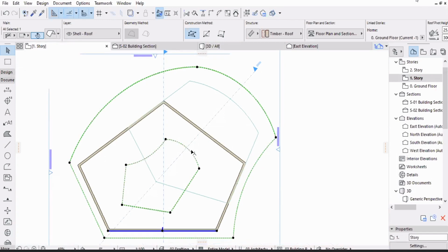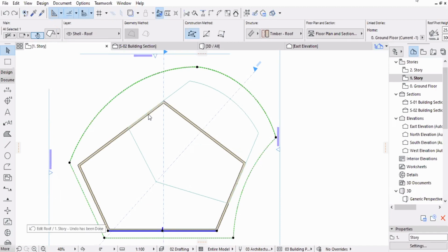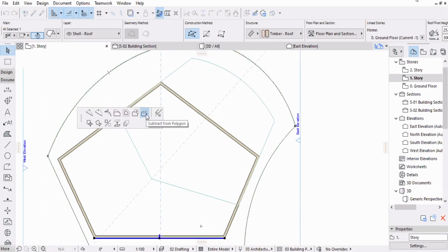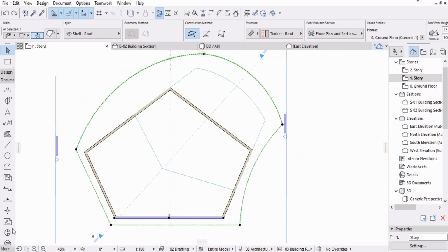But let's say you have a weird shape. You don't have a kind of thing like what is being allowed by this. This particular subtraction allows us to draw things in a very limited manner. You can either draw combinations of straight lines and curves and other things, right? But let's say you have an altogether different shape. In this case, I want some shape which is much more curved and organic for the skylight, let's say. So we'll do this using the spline tool under more.